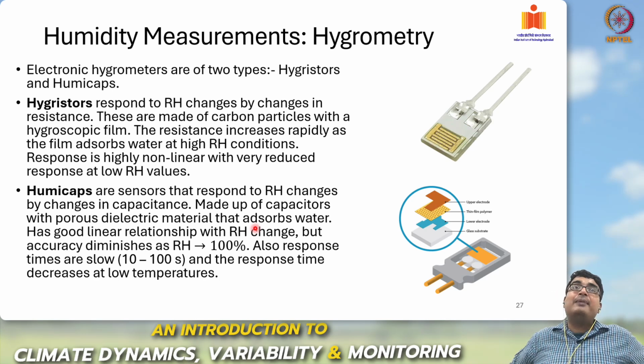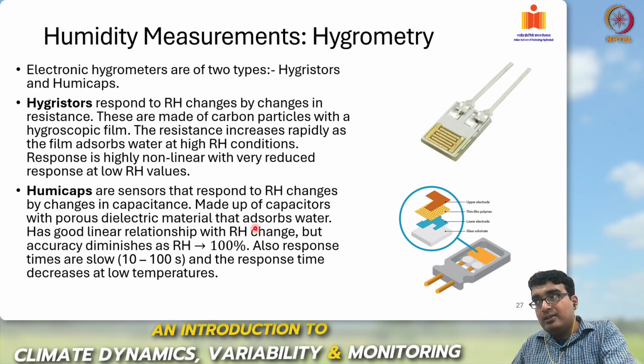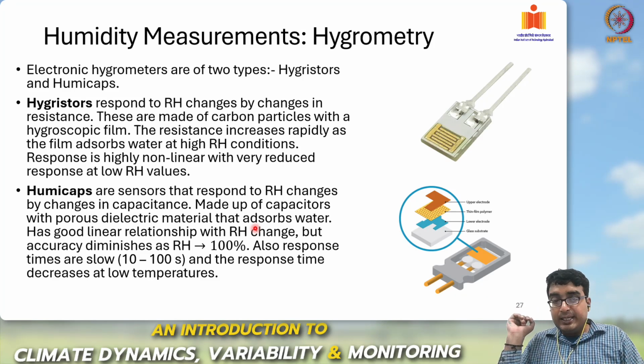Also, the response times are slow. It takes a lot of time for the adsorption to happen and the capacitance to increase. Response times are 10 to 100 seconds. And the response time also increases at low temperatures, so that is also a problem. So those are the two disadvantages, but the advantage is you are getting a linear response.